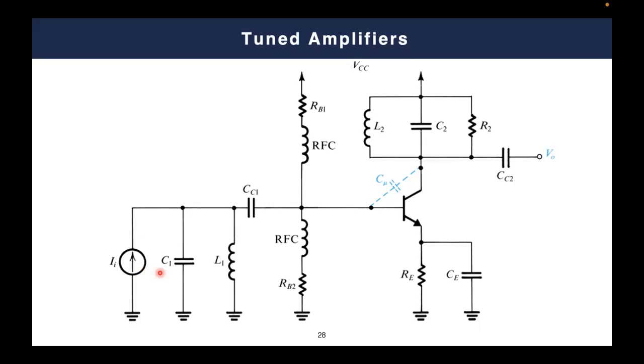and you can easily reject your noise by simply tuning the values of L1 and C1, so you can adjust the band of your filter by simply adjusting L1 and C1. So this is the basic concept of a filter. But this topology has a very main drawback, and this is actually somehow a hidden drawback.